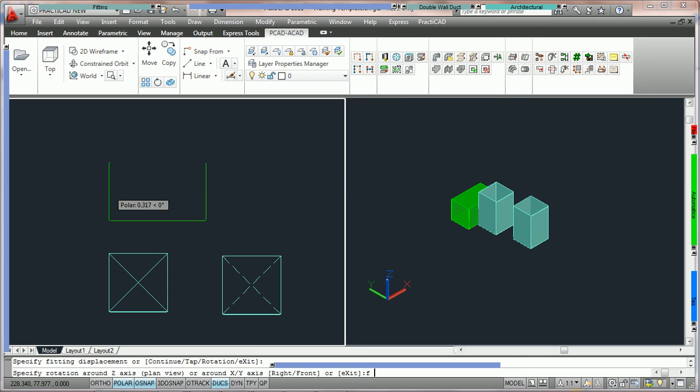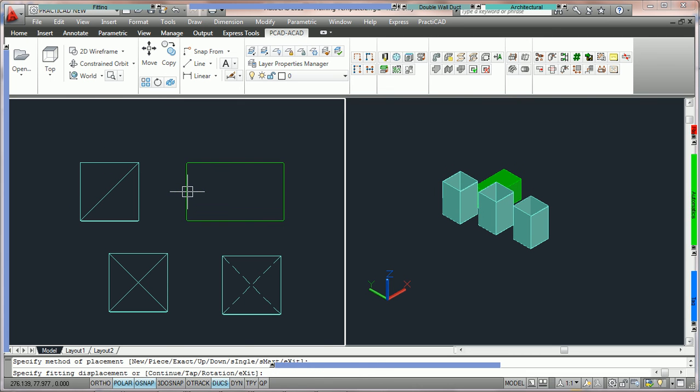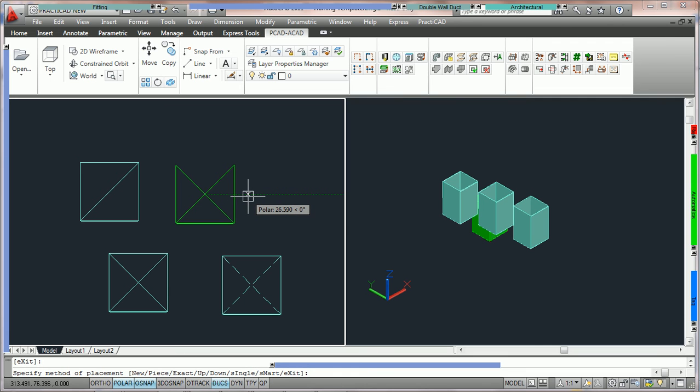we're going to put it on the drawing, we're going to hit F to rotate it, and we're going to rotate this one up. So I'm actually going to type in 270 to rotate it up. We're going to click on the drawing. You can see that the return symbol is there. Now we're going to place one, and we're actually going to hit F, and we're going to rotate the duct down. You can see that it's indicating the X symbol.